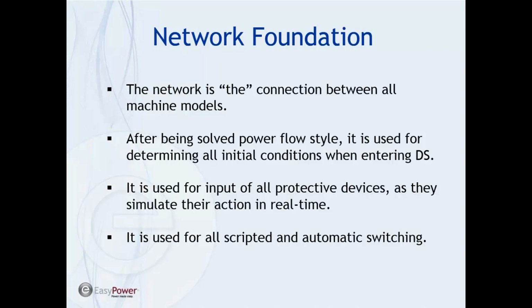After it's solved power flow style, that is, like in power flow with a swing bus, it is used for determining all of the initial conditions when entering DS. So all the machines extract their terminal conditions of power, real and reactive power, to initialize the models.